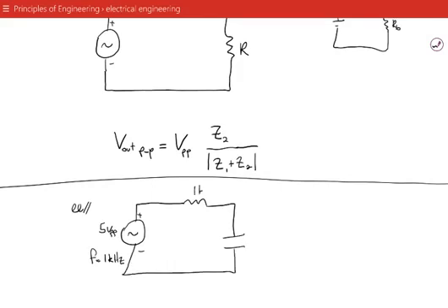And the resistor, let's say, is 1K and the capacitor is 10 microfarads. Then the voltage out, peak to peak, and remember, the voltage is going to be changing because we're going to be putting an AC signal in. So that's why we're referring to peak to peak, which is twice the amplitude of, say, the sine wave or whatever we're putting in. The voltage out, peak to peak,